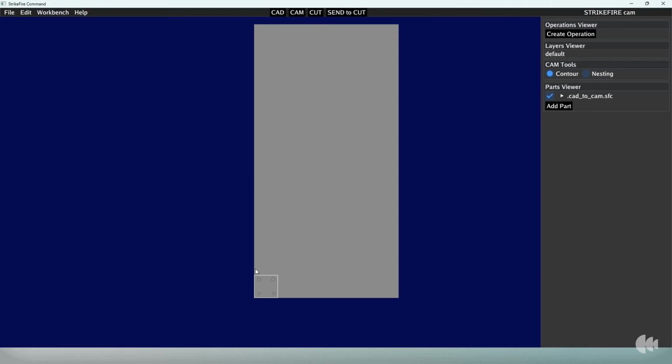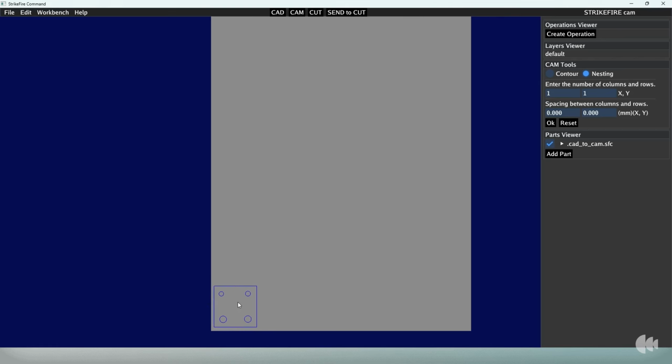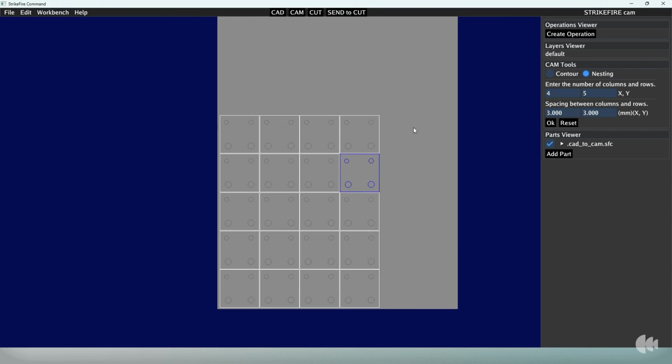That will then put the part straight onto the nesting component. If you click onto nesting, we can then move that part. We can also rotate it 360 degrees by holding the tab button, and we can also then just use our simple grid nesting. So if we want 5 parts by 5 parts, radial spacing, should make that 4. It will then put it into a grid pattern.